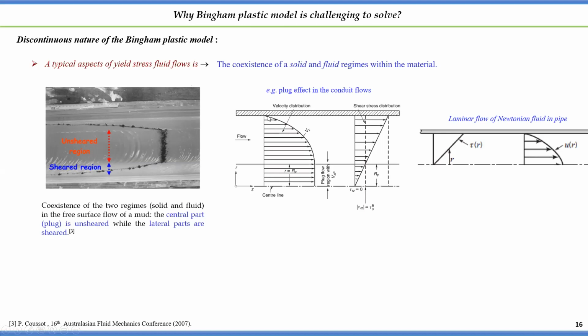But when you move towards the solid boundary, because of the presence of this boundary and the boundary condition, which is nothing but the no slip condition, velocity is zero. So the velocity will vary from the velocity in the plug zone to zero velocity. So there is a velocity gradient. Here we are able to see the deformation, that means a velocity gradient exists.